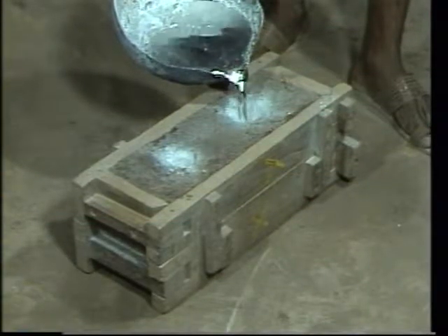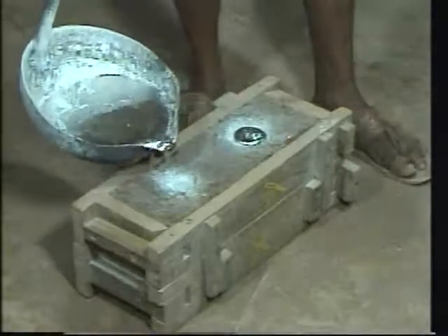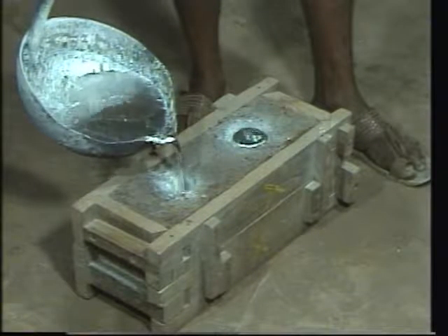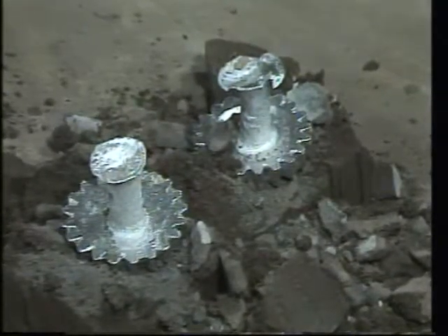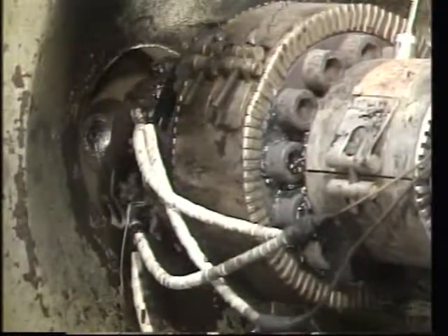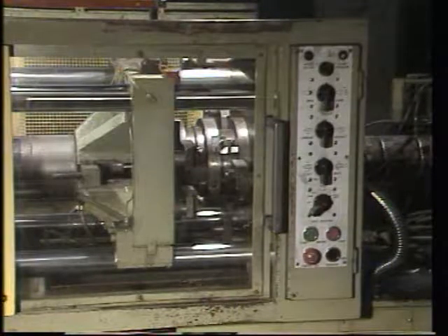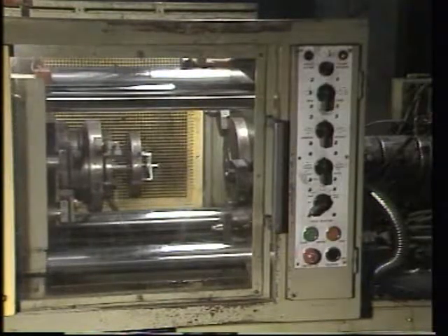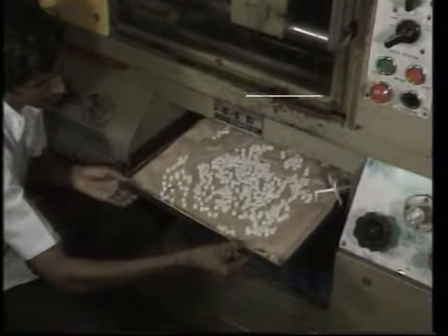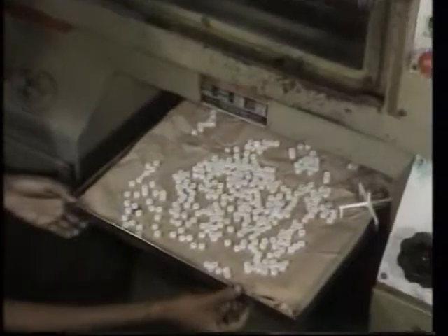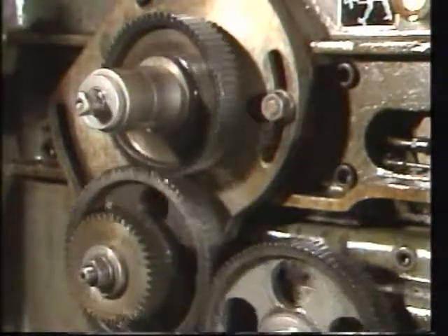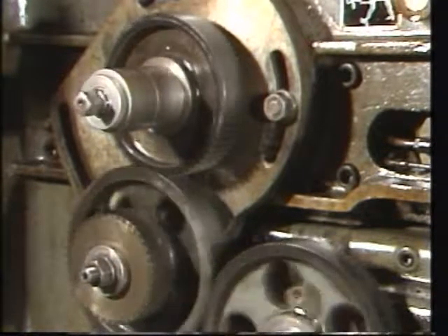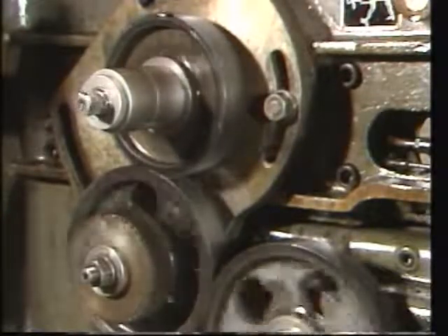The primitive method is the sand casting process, which produces coarse quality gears. The cast gears are for slow speed applications and where high accuracy is not a prime factor. Gears are also produced from plastic materials by injection molding. This method is employed where quietness, insulating properties, and moderate strength for light services are needed. To transmit high torque at greater speed with accuracy, gears made by metal removing process are preferred.